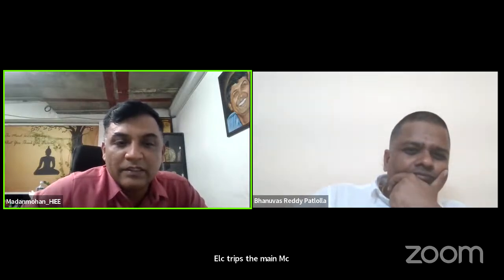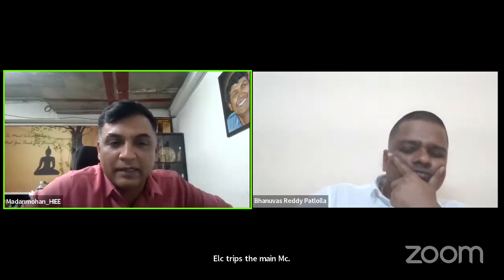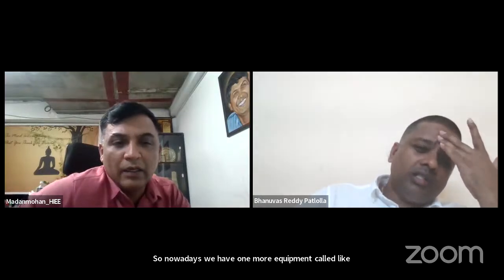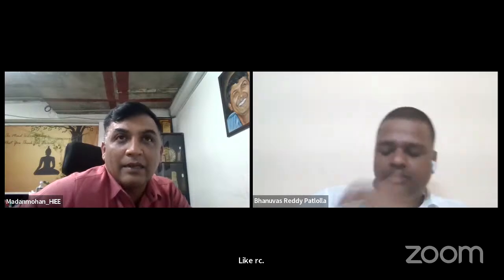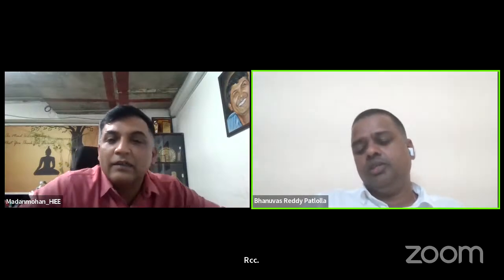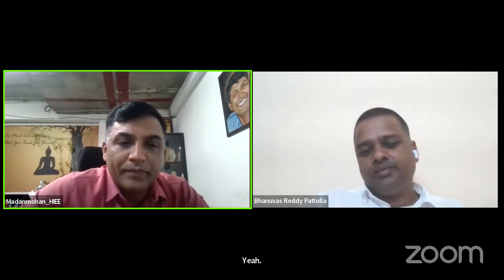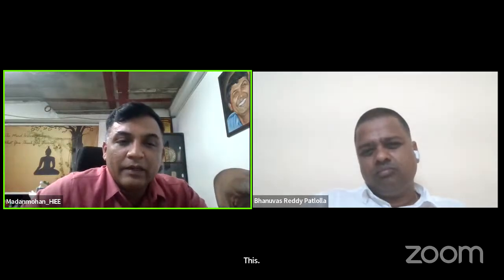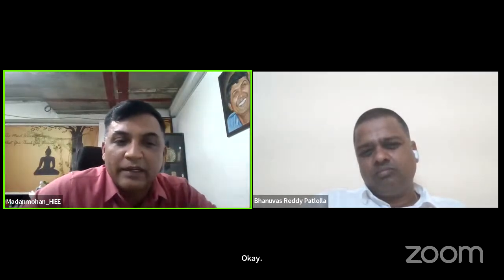That's where your system can be protected from the earth leakage conditions. Nowadays we have one more equipment called RCCB. ELCBs are discontinued, no more in use. RCCBs are working now. Everything is given within the breaker. There is also a residual breaker with overload and short circuit protection, called RCBO.